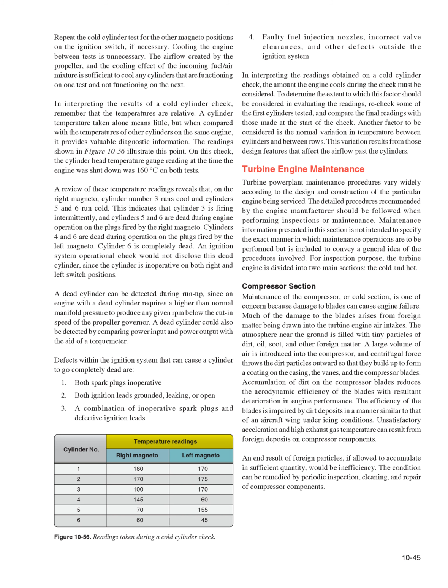Accumulation of dirt on the compressor blades reduces the aerodynamic efficiency of the blades, with resultant deterioration in engine performance. The efficiency of the blades is impaired by dirt deposits in a manner similar to that of an aircraft wing under icing conditions. Unsatisfactory acceleration and high exhaust gas temperature can result from foreign deposits on compressor components. An end result of foreign particles, if allowed to accumulate in sufficient quantity, would be inefficiency. The condition can be remedied by periodic inspection, cleaning, and repair of compressor components.